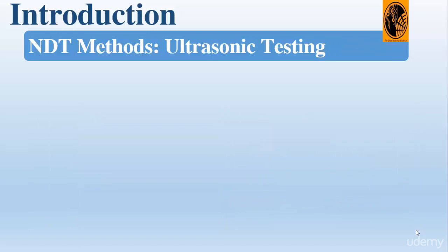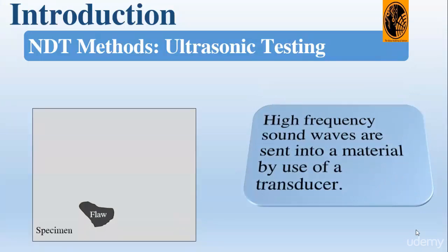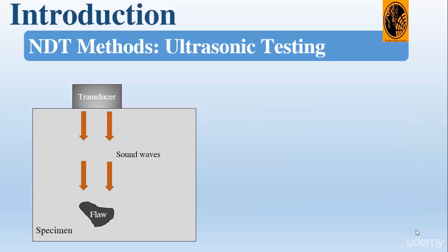Now let's see the ultrasonic testing technique. The main principle of this technique is to generate a high frequency sound wave inside the material. So as you can see here, we have a specimen with a flaw, and this transducer generates sound waves of high frequency.